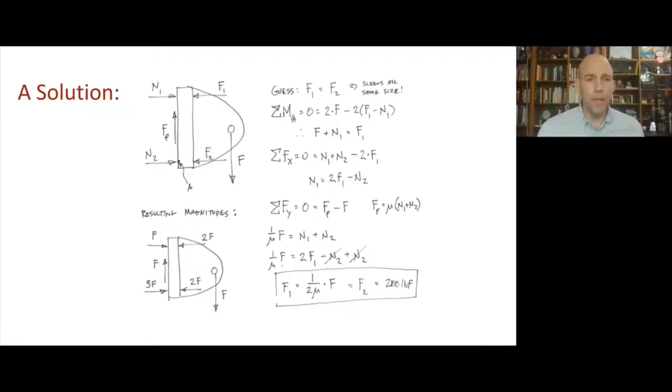And so the way that I've characterized this in this free body diagram is to say, okay, we've got one normal force from the screw and a normal force from this screw at the bottom. I'm saying the two at the top have the same force, the two at the bottom have the same force. That's one simplifying assumption here. And then we've got a force from the wall onto our part that we're characterizing with a point normal force at the top and a point normal force at the bottom, and then a friction force that is along the surface in the vertical direction.